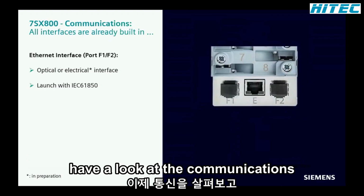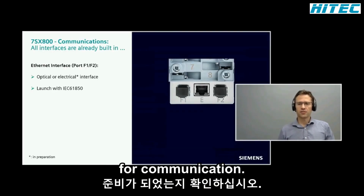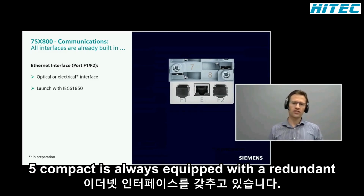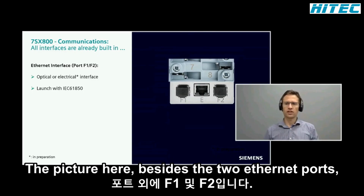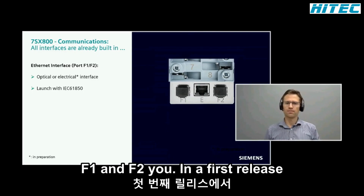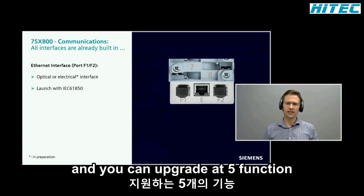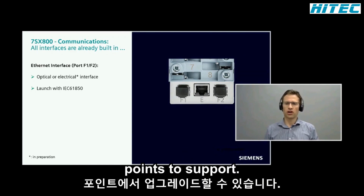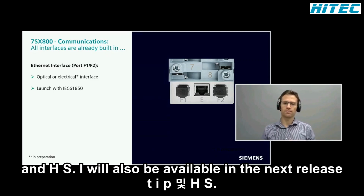Now let's have a look at the communications. To make sure that the relay is ready for communication, the SIPROTEC 5 Compact is always equipped with a redundant Ethernet interface. The picture here shows the 2 Ethernet ports, F1 and F2. In our first release, the relay will always contain an optical Ethernet interface. It can be used for remote DIGSI access, and you can upgrade it via function points to support the IEC 61850 protocol. The redundancy protocols RSTP, PRP, and HSR will also be available.